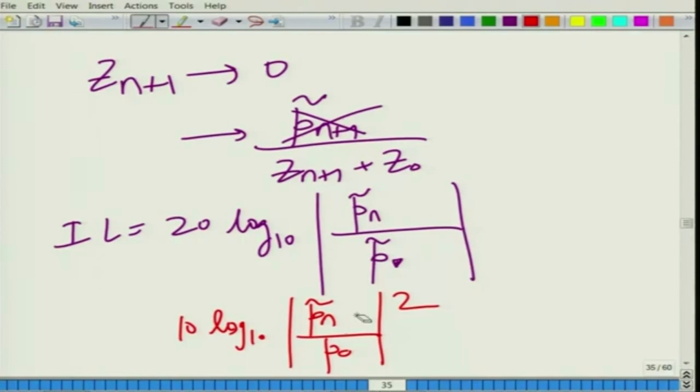So, if we want to start from analytical principles or some numerical scheme, not only do we need to do the muffler wave propagation modeling within the muffler, we also need to know the source impedance and the source pressure. Fortunately, a lot of work has been done in this field, and there are some well known empirical expressions which we can use in the codes to numerically predict the insertion loss.